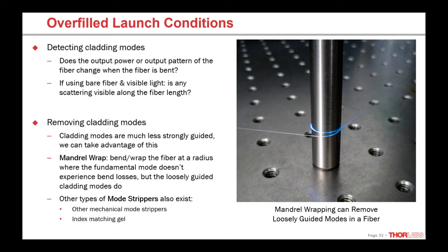There are other methods as well, things like, the general term would be mode strippers, things like index matching gel that can destroy any kind of total internal reflection happening at that coating to air interface and get rid of those modes.